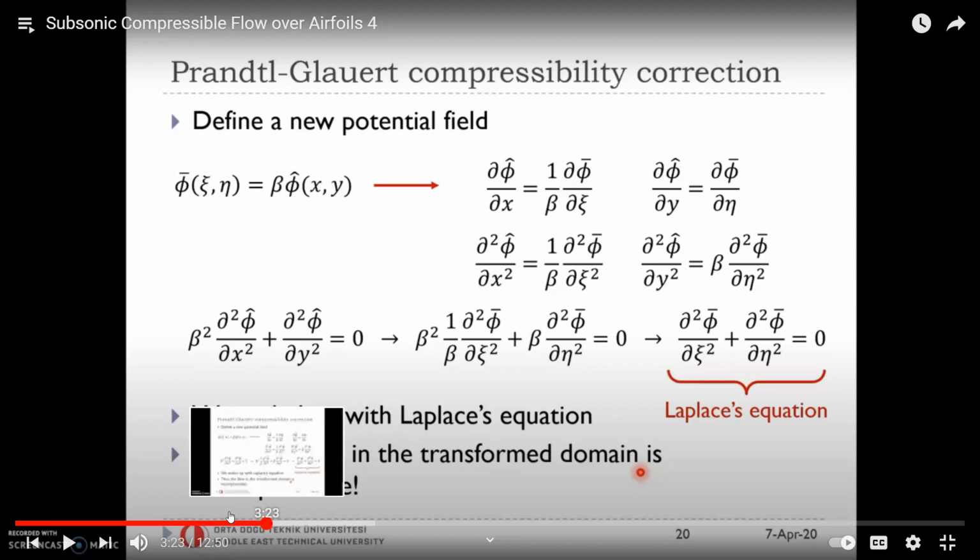we know how to solve Laplace's equation in general, but if we solve this equation with these parameters, it is very much related. Since the incompressible flow is governed by the same equation, but with different parameters, they must be related. That's what we are trying to do. The solution of incompressible flow and the solution for compressible flow that we obtain from this phi bar equation must be related to each other. So what is that relation?